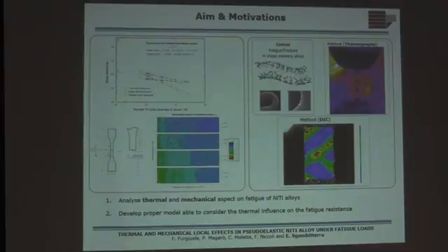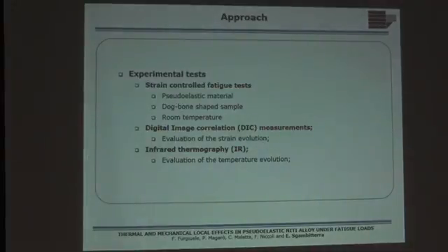point of view. The main approach of the work is based on a strain-control fatigue test performed on the pseudoelastic material, and we used two full-field measurement techniques to evaluate the strain evolution during the load history and to evaluate the thermal evolution during the load history.